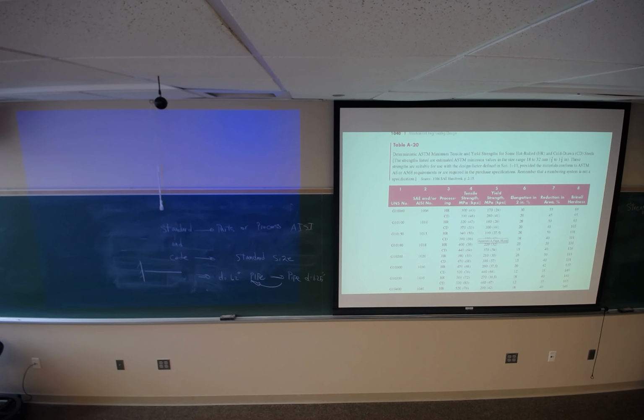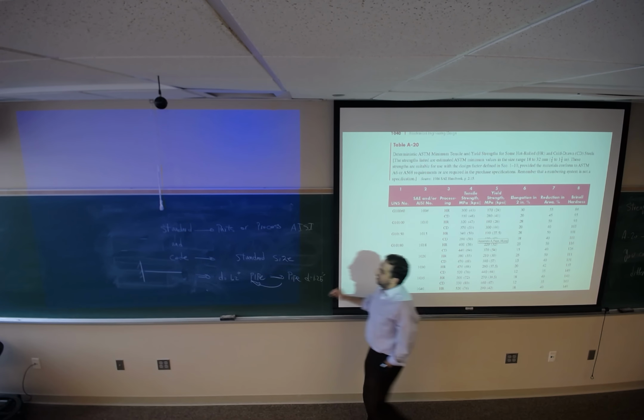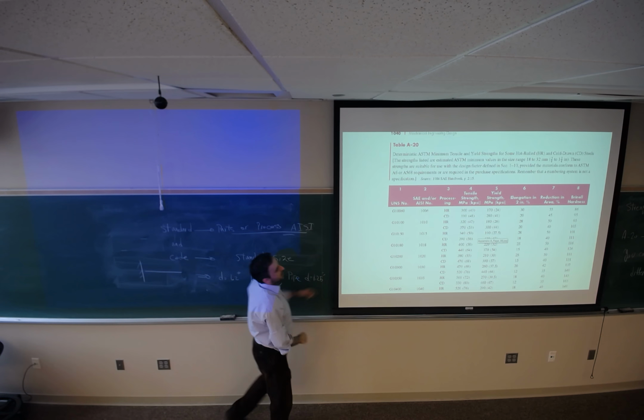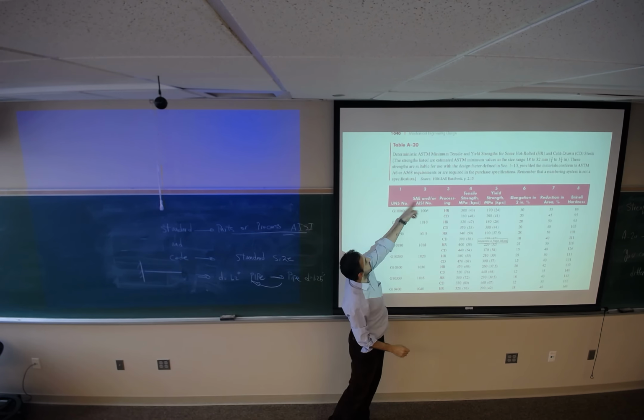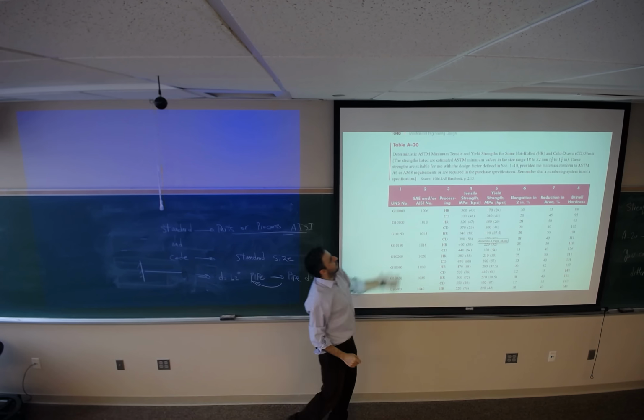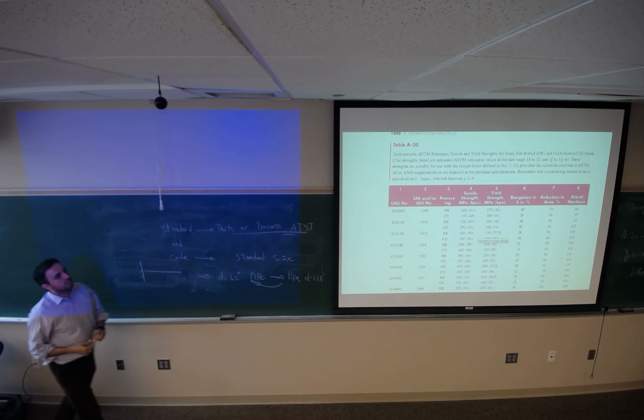From 820 to 827, you can find the strength of different materials. And the materials have been labeled by different standards. One of them is AISI, the other one is SAE, or the other one is UNS. Depending on which standard you are using, they have a different name.